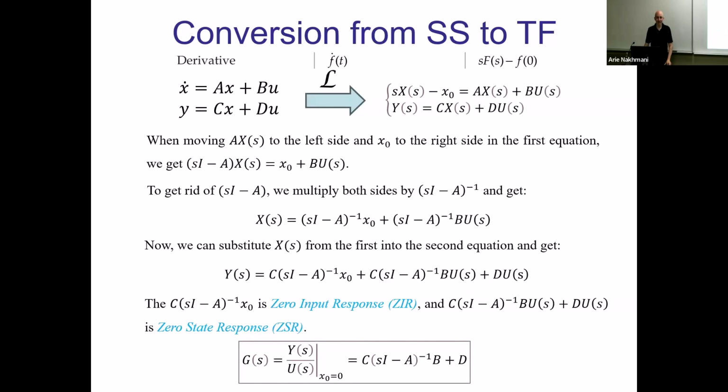Okay, so in the last equation that we have for the transfer function, without knowing the dimensions of A, B, or any other matrix, can we directly comment that it will be a scalar based on the dimension? Only for SISO systems it will be scalar, yes. But if, for example, D is a 2 by 2 matrix, you might have actually a matrix G. So G will be a matrix of transfer functions. The dimension of D will define the number of elements or outputs.